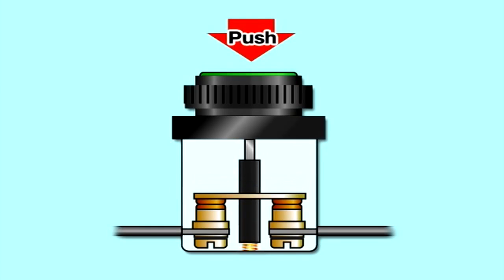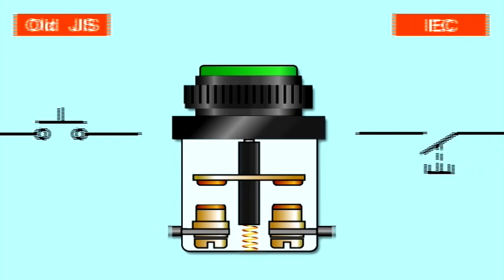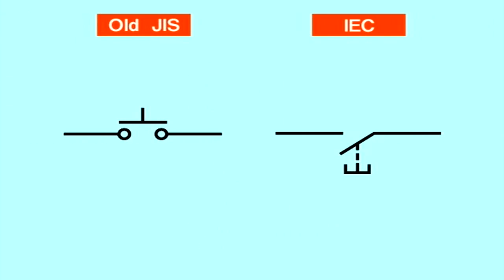The circuit remains closed and the on state is maintained only while A contact is in operation. Because of this, the indication NO, or normally open, will often appear on the A contact terminal. The A contact push button switch closes the circuit when the button is pressed and opens the circuit using spring force when the button is no longer being pressed.